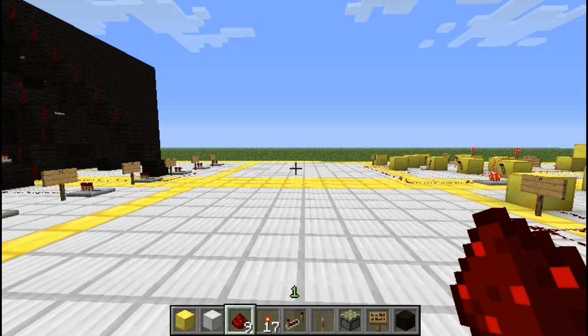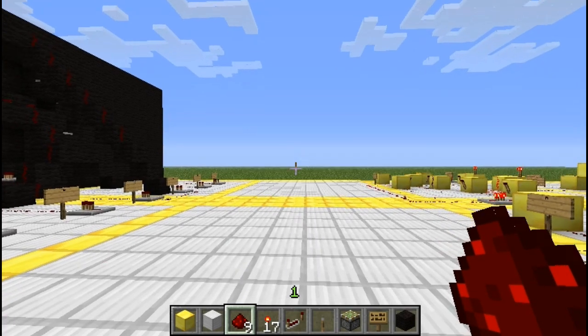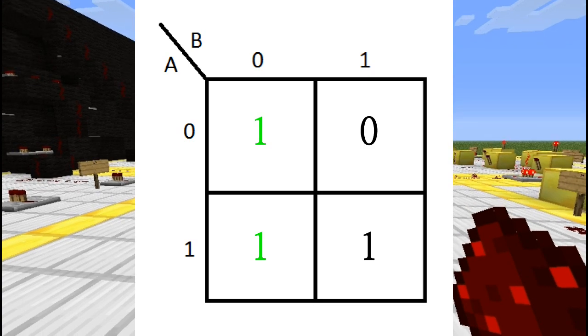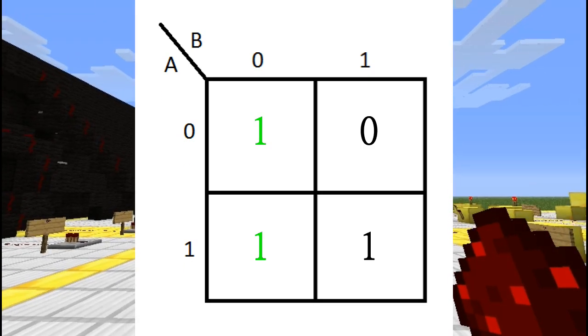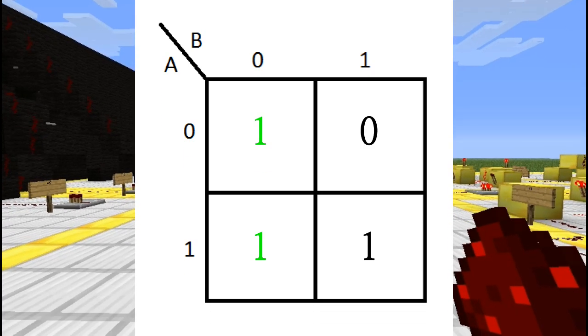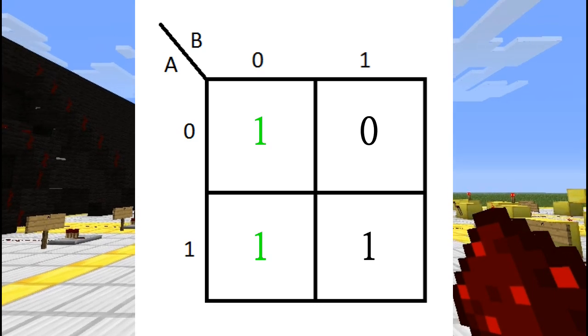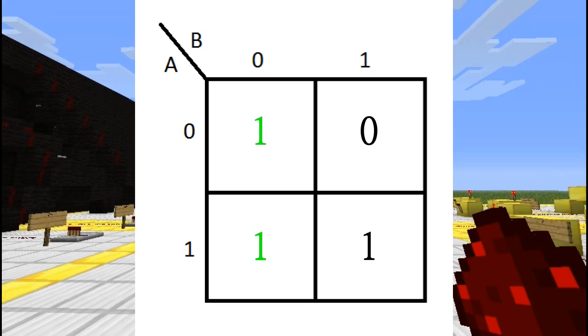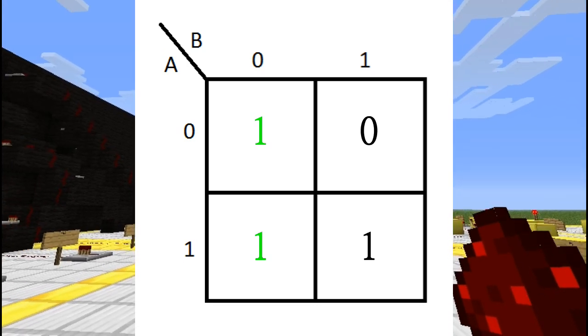Then we can use this box to determine the gates that are required to create D0. So we take this box of 1 and 1, and we can see that regardless of the value of A, one of the possibilities of the values of D0 is B inverted, which is represented by this 0.